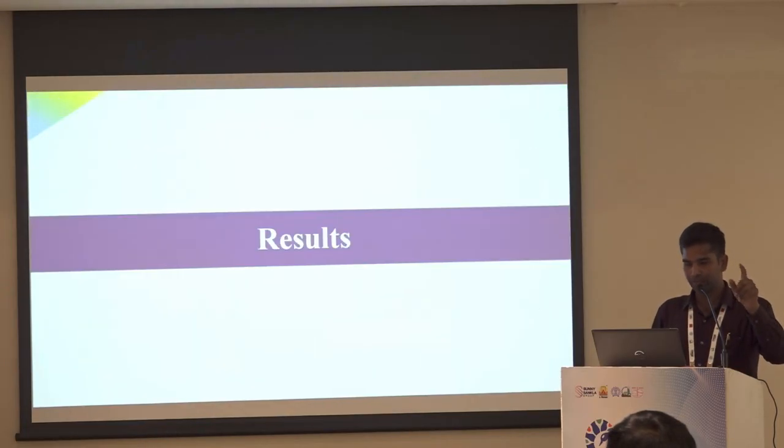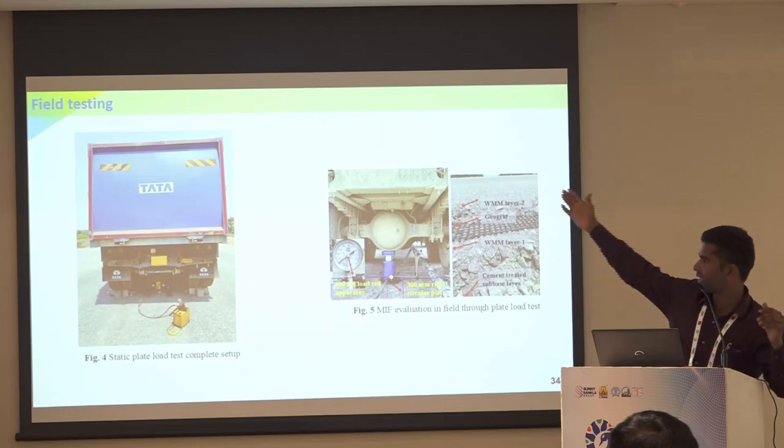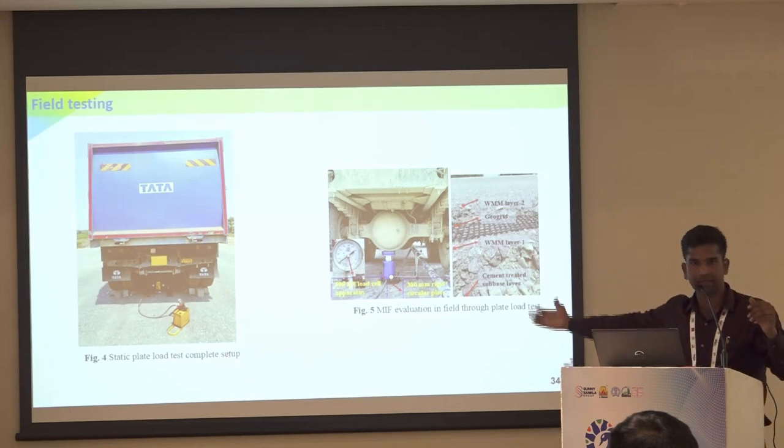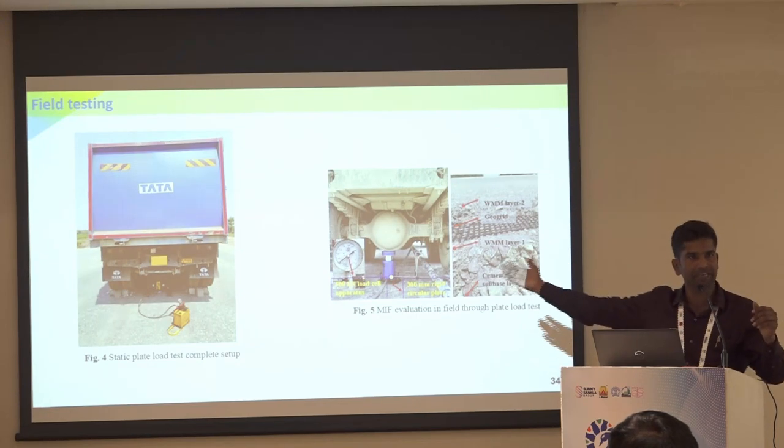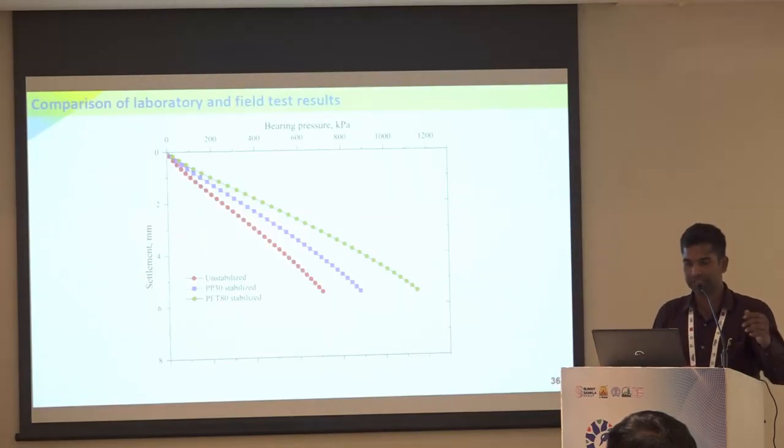And we have used a simple static plate load test to evaluate the modulus value. It's simple equipment where we have 40 tons of load on a truck, and then we apply a maximum of 10 tons using the static actuator that could quantify our results.